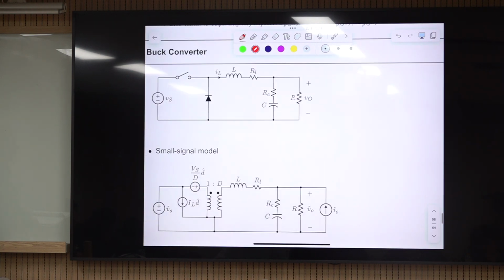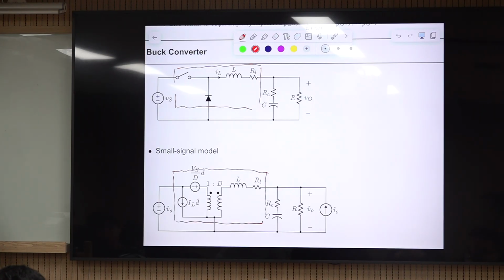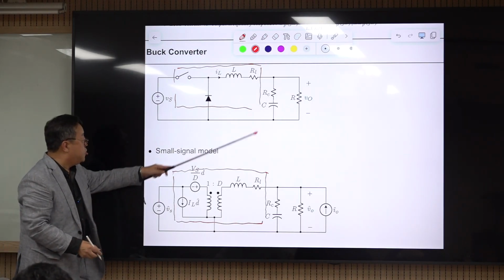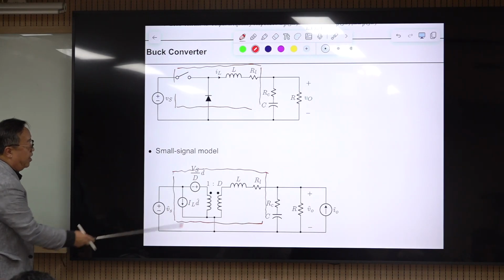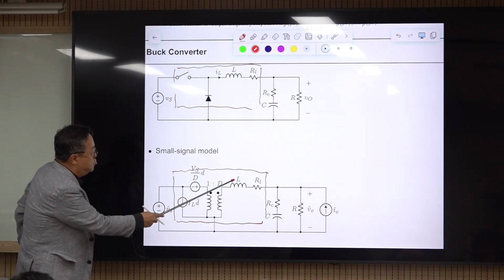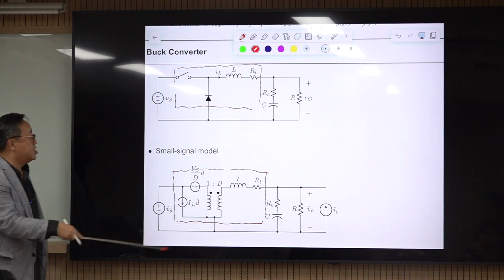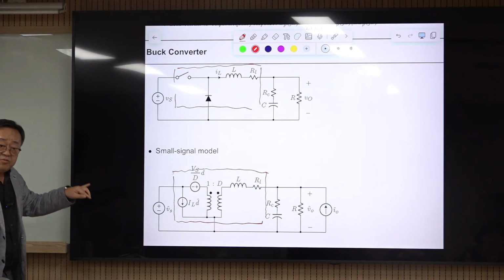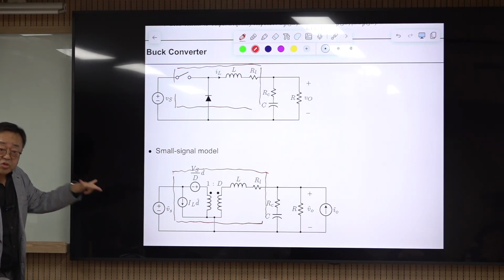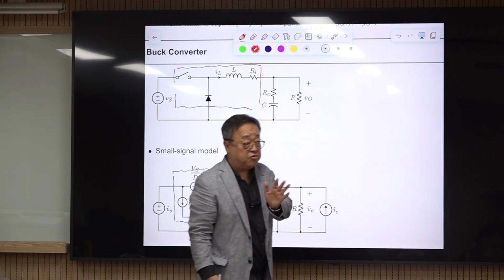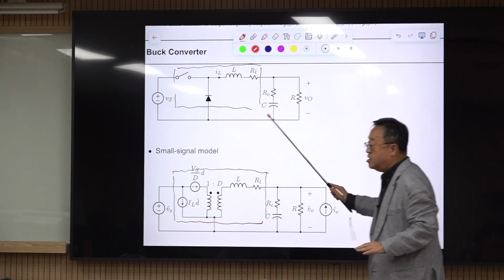And for the converter case, you replace this PWM switch, including this resonant inductor and so on, with a pin-to-pin replacement of this functional block by the small signal model of the PWM switch. Everything will be changed to small signal variables and S-domain variables. So I need to use sL and 1 over sC here, but this one remains the same. So this is the small signal model of a converter. It is derived through averaging and linearization. Those steps are not shown here, and we'll go back to the derivation of these things. But understanding this is enough for now.